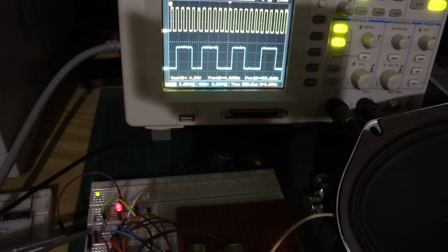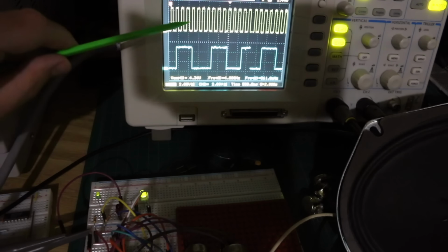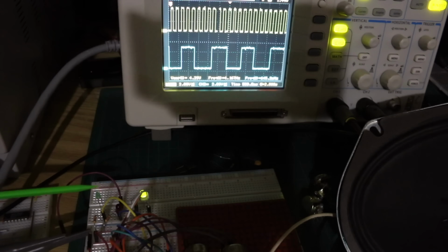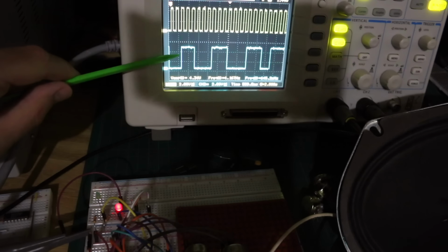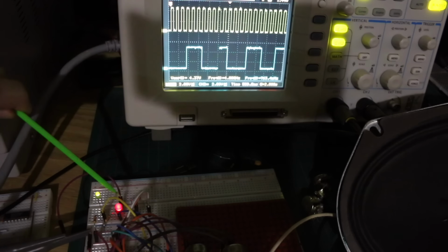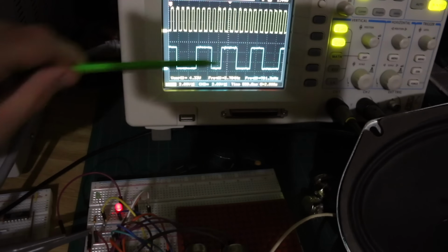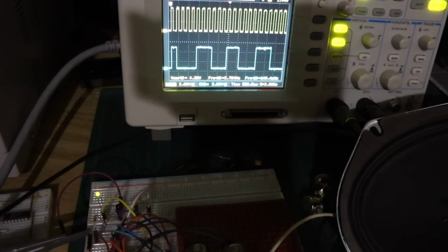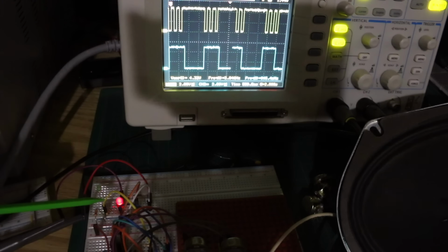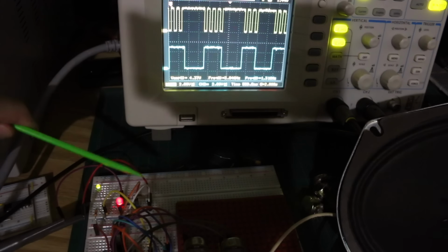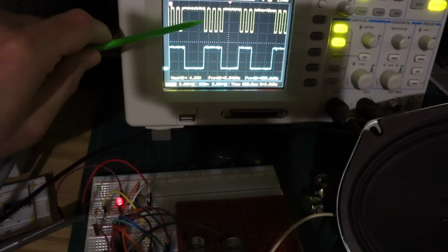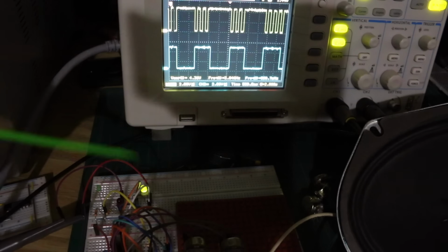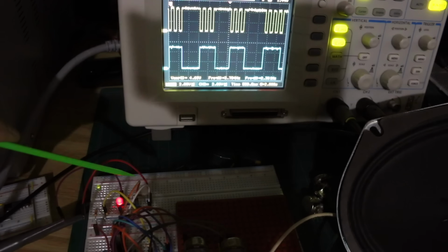I only have a 2-channel scope, so we have the faster oscillator on the top, representing the faster blinking light, the slower oscillator on the bottom, representing the slower blinking red light. So I'll take the top channel and put it on this output third LED. So on the bottom trace we have the red LED's oscillator, so this output LED on the top trace. So that can allow you to sort of generate custom intervals or waveform patterns.